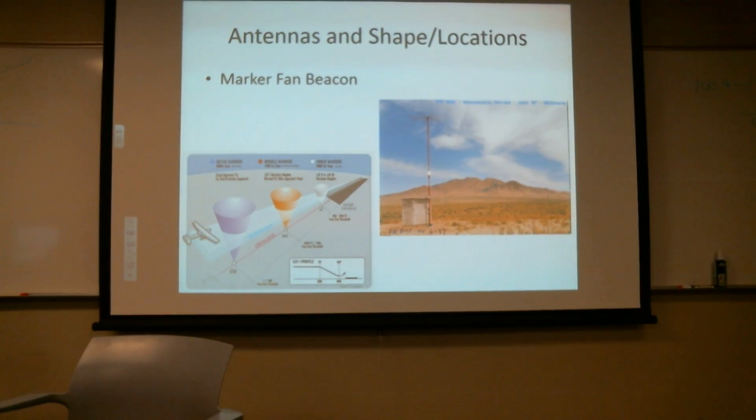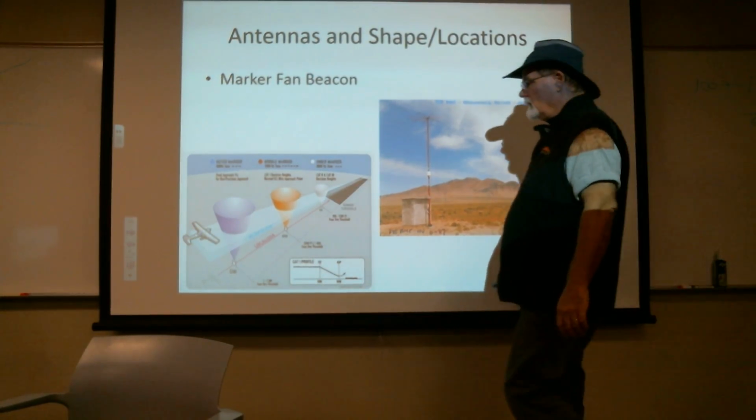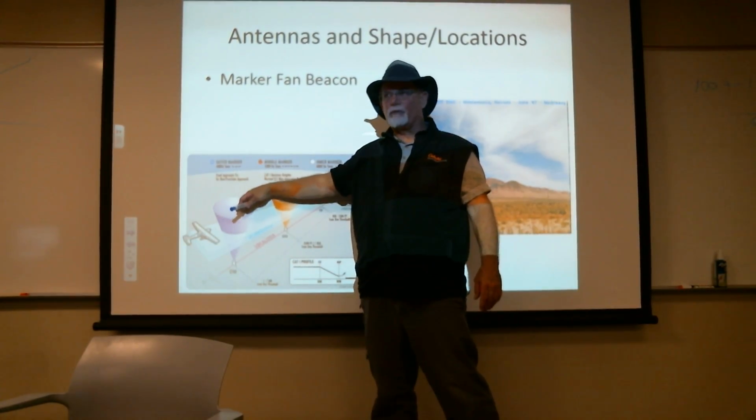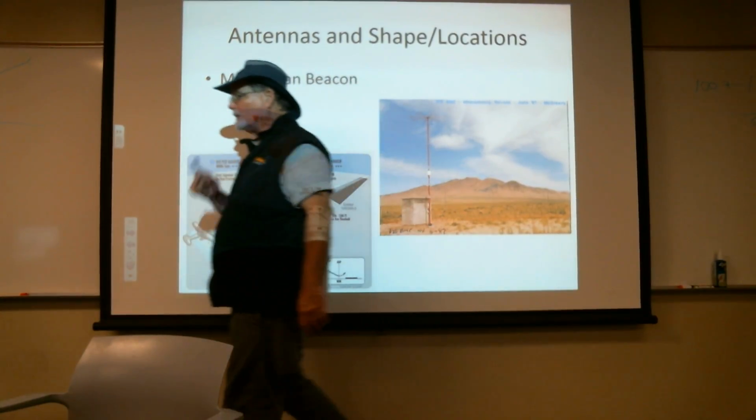But the other thing we're going to do is the device that's listening to this is going to listen for that tone, 400 hertz. And if it hears the 400 hertz above a certain threshold, it'll start causing a light to go beep, beep, beep. In this case, it'll be a blue light starting to flash, and you'll hear it on the audio if you've got the audio set up. Okay, then it'll start getting weak again. And then a little while later, the middle one will start coming, beep, beep, beep, get really, really loud. So that gives the pilot some distance information and a double confirmation that they're probably in the ballpark, headed towards the end of the runway.